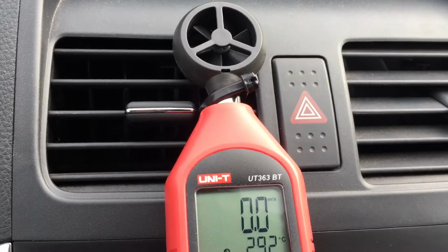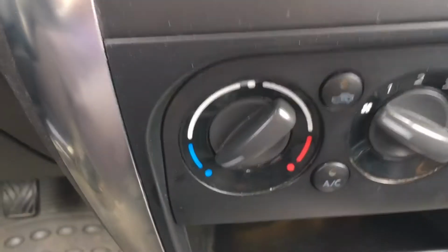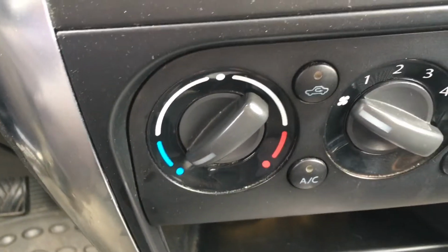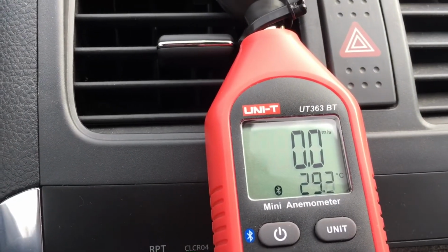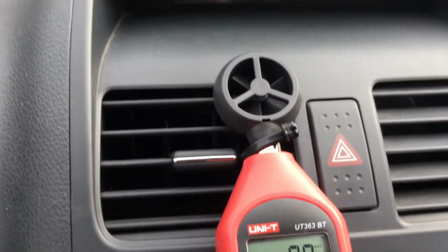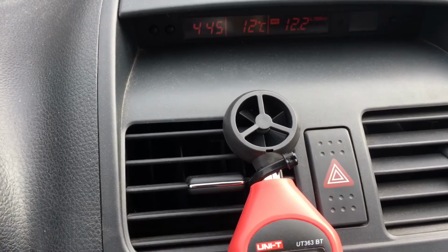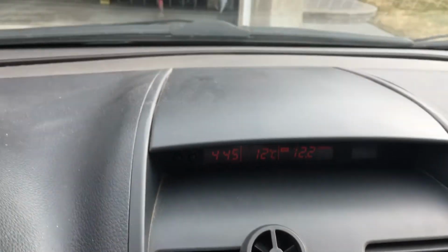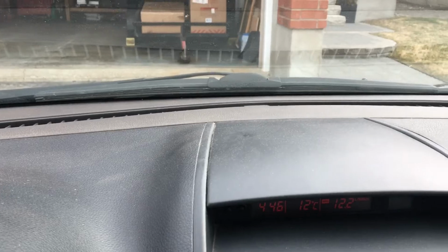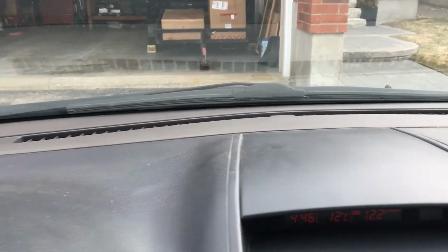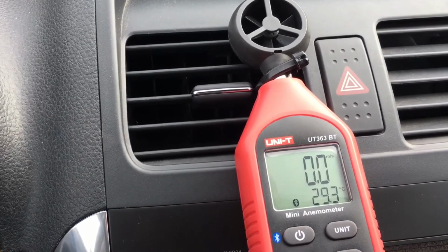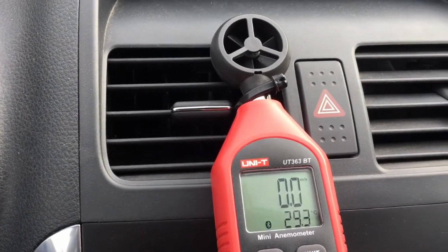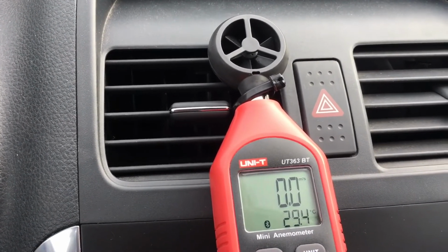So yeah, just monitoring the plenum flow out of the ductwork there. You can see I'm just set on cold and the fan is in the off position, so this flow should be strictly a function of vehicle speed, basically. Of course, the faster the car goes, the greater the pressure will build up at the cowl area, and it should actually increase the airflow. So that's what you read in textbooks anyway, so let's convince ourselves of that.